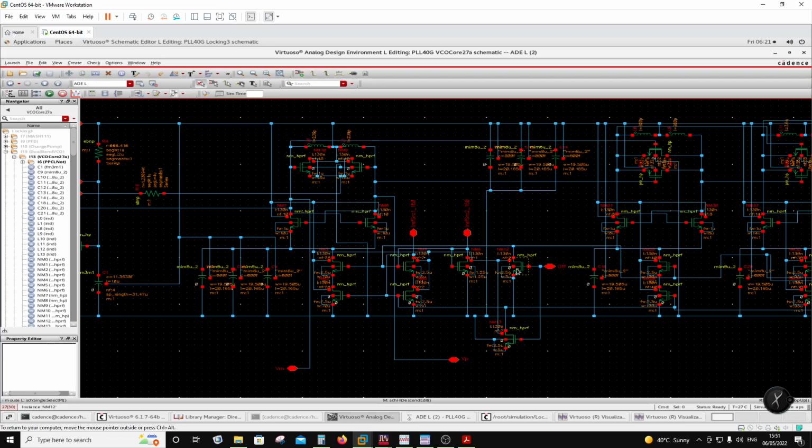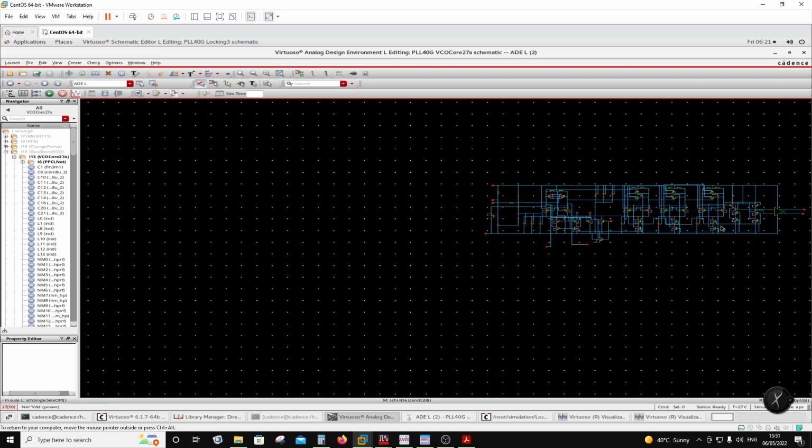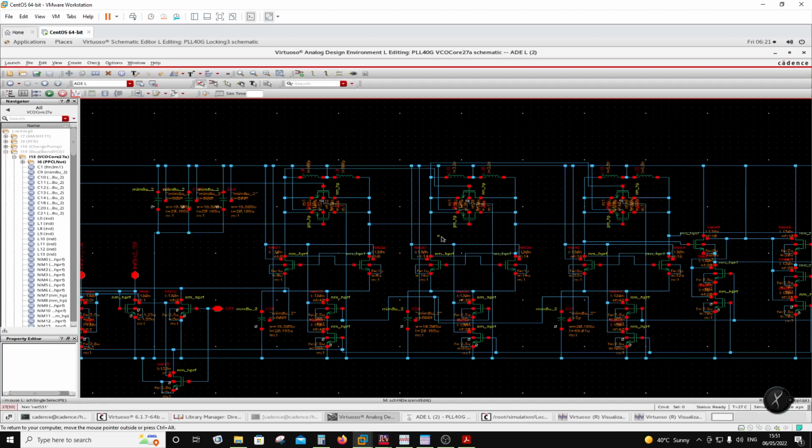If the inputs are high, then these two lines are pulled down. That means that the current mirror is not working, and so the current is cut off to the VCO and the three injection lock dividers. So basically you are switching off the VCO. So the band which is not required is switched off. Again, this is done by the L/H line. So the L/H line is going to turn off one of the VCOs depending on which band you choose, right?